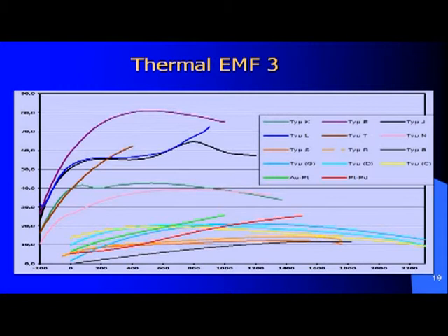It is a Russian standard, from a GOST standard, and this one is maybe used up to 2,500 degrees centigrade, and it's quite stable, but for all refractory elements, take into consideration that the uncertainty is near to 1% of reading.